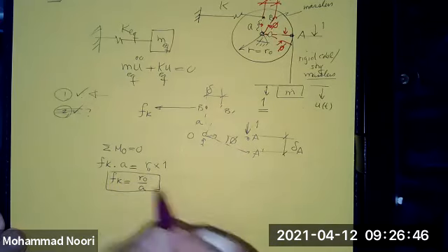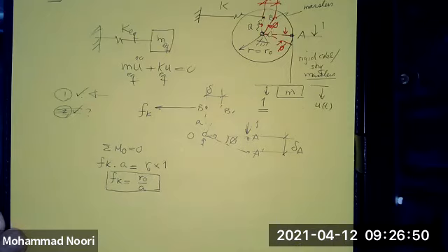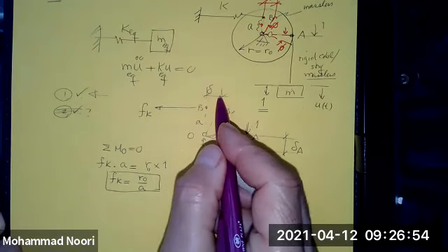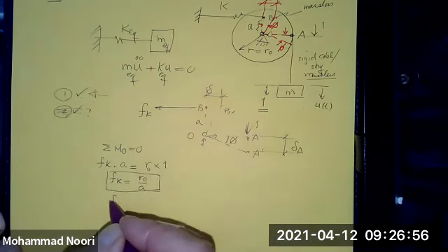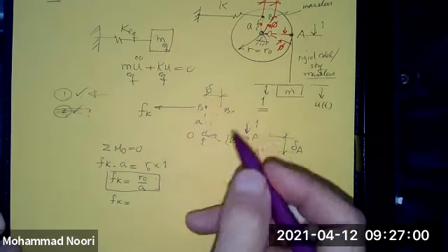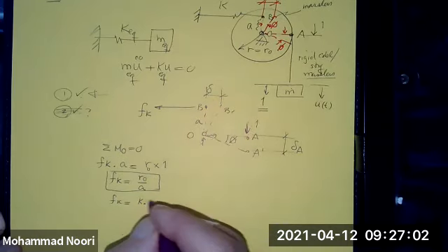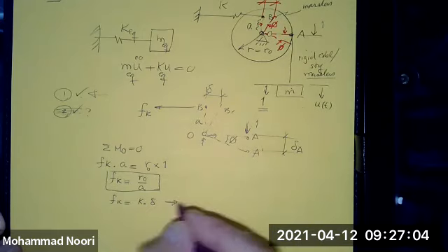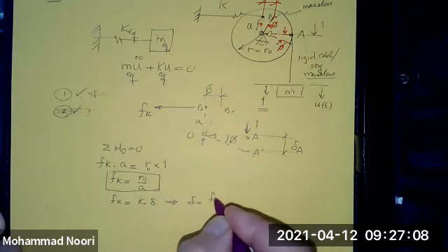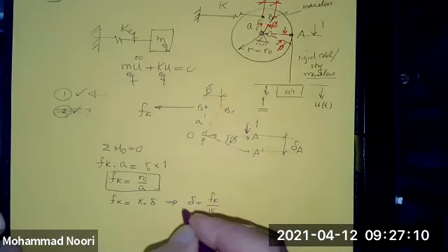However, you do know that this is going through a displacement, right? In other words, f of k in terms of the displacement that it's going through is k times delta, or delta is f of k over k.